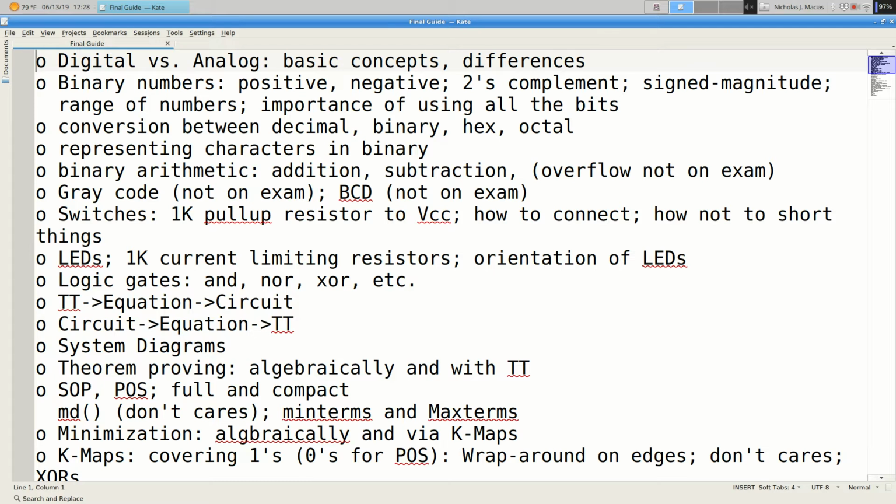So digitizing is less accurate in some ways, because if we use a bunch of these binary values to represent something, if we have 8 binary digits, we can represent 256 different things. Well, if we break 5 volts into 256 buckets, we can only represent a few millivolts from one bucket to the next. It's not exact.